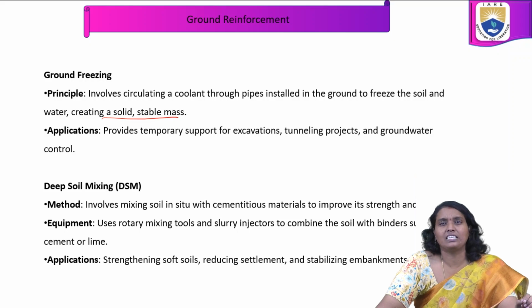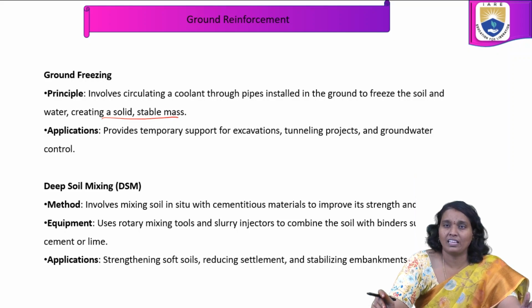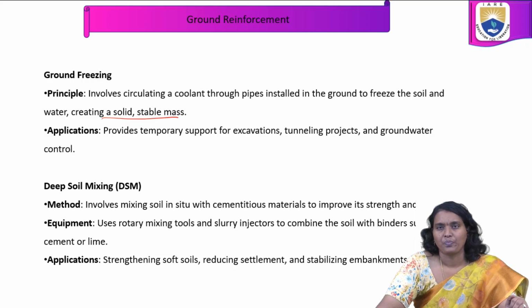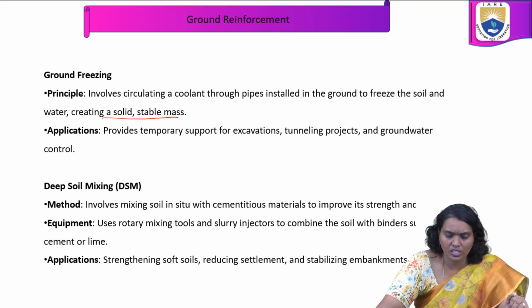And the next one is deep soil mixing. Whenever there are deep excavations, whenever the depth is more, in such cases we choose this type of ground reinforcement technique, that is deep soil mixing. This method involves mixing soil in situ with cementitious materials to improve its strength and stability.